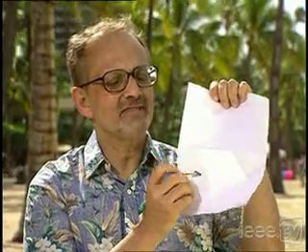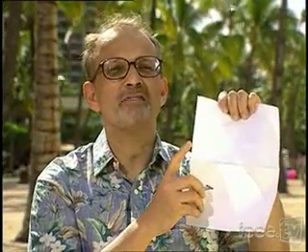It's not yet digital. Now when we bisect it, we decide, does the voltage lie below or above the halfway point? That's a decision. And we give that decision a bit. If it's below, we call it 0. If it's above, we call it 1. Now we can focus, once we've narrowed it down to the lower half of the ruler, on this portion, and we repeat the procedure.